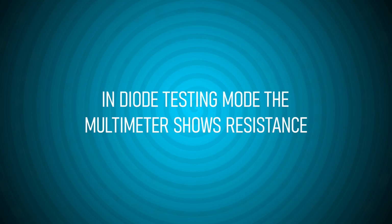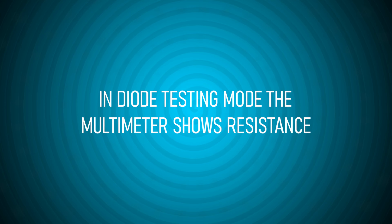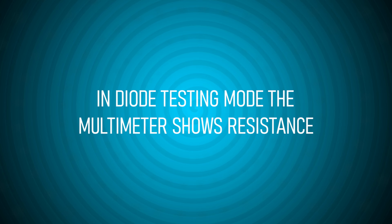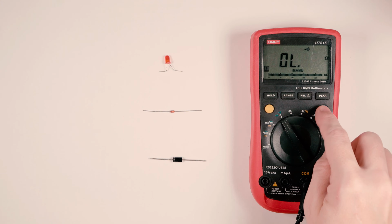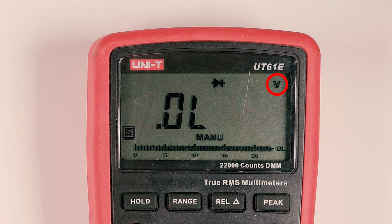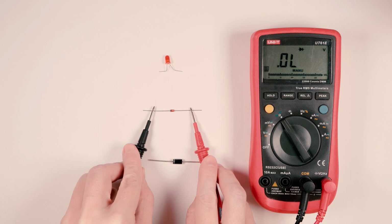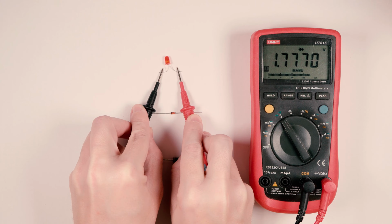Myth number 6. In diode testing mode, the multimeter shows resistance. Actually, no. In diode testing mode, the multimeter shows voltage. The voltage that drops across the diode you are measuring. And proof of this is the V icon in the upper right corner of the device display. For example, in this case, the drop is 0.17 volts, since it's a Schottky diode. On a regular diode, the drop is 0.73 volts, and on an LED, it drops 1.7 volts.